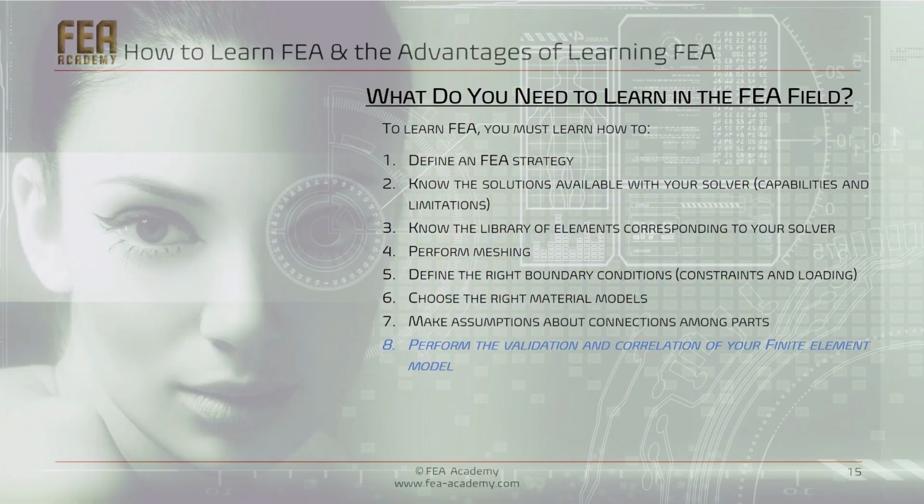You will have to learn how to perform the validation and the correlation of your finite element model. This is very important because it will give you confidence in your results, but also to your client and the final user of the FEA. There are methods available to validate your FEA, so learn them and use them. If you work with test data, you will have to learn how to correlate an FEM and how to adjust and calibrate your simulation.